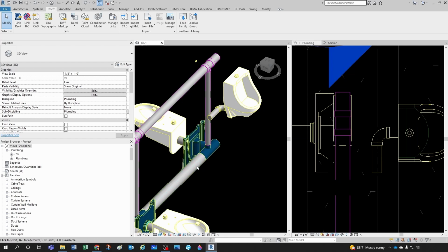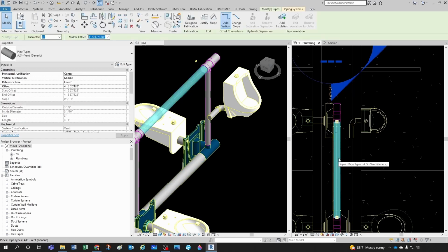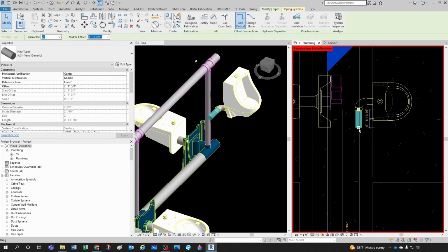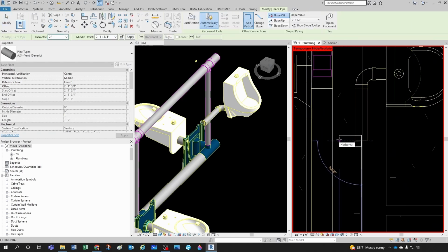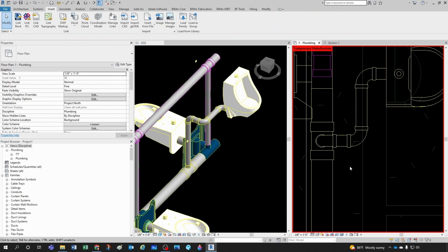But in my case, I think it's going to be easier to just connect it to the main line. And one little trick I use a lot is I click here and I temporarily hide this using HH. You need to make sure you have your keyboard shortcuts set up properly, right? And then once I make this connection, I can simply do HR for hide restore.